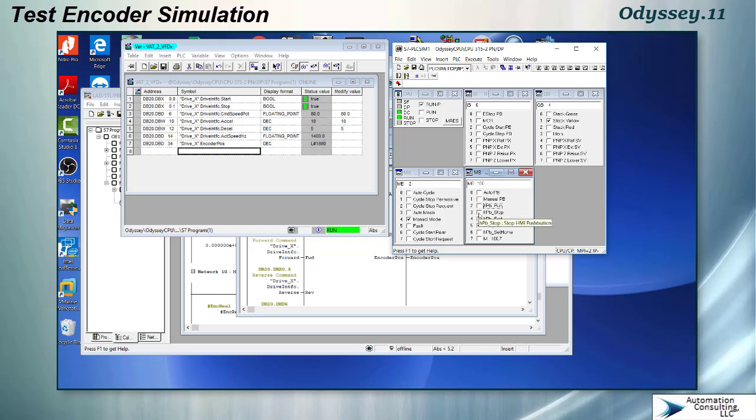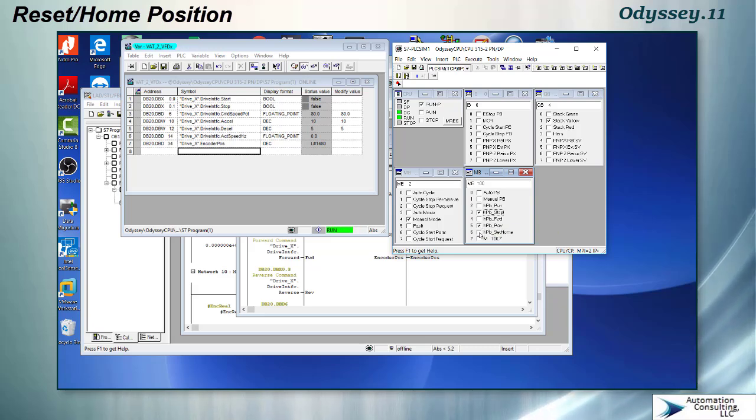So we will stop the drive, we ramp down, and we are at currently 1480 pulses. And then if I want to, I can reset this to 0. So I set home. Typically what goes on here with homing is you would move back to a sensor of some kind, an external sensor on the actuator, and when you hit that sensor you would say stop, and then once the actuator was detected to be in the 0 position, then you would set it home, and you wouldn't be doing that with a push button, you'd do it with a command in your auto sequence.